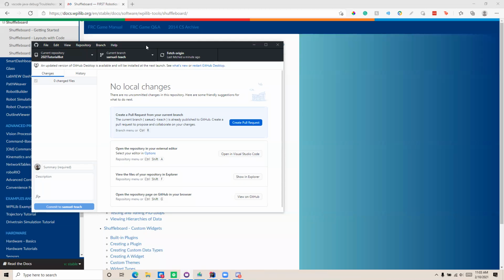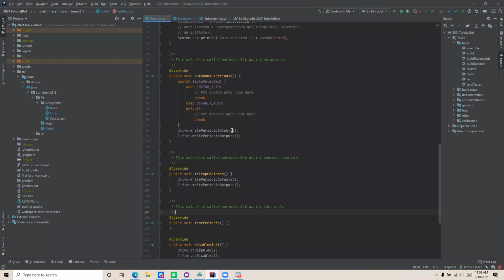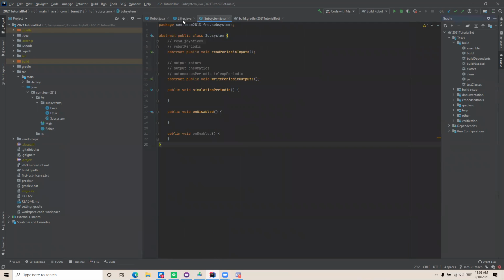All right. So if you remember last time, we were working on PID. I taught you guys the concepts of PID, how it works in the background, and how to tune PID, like a tuning process for PID. And then I found in the WPILib simulator they have physics simulations, which means we can actually do a little bit of that within our own computers without actually having access to Doom Turtle or another robot. So I already wrote the code last night and we'll be going through it and following it.